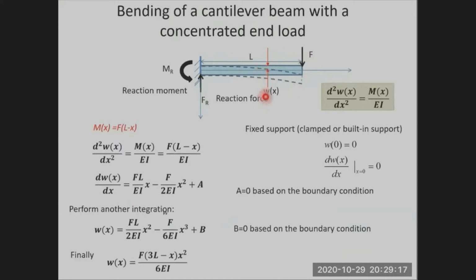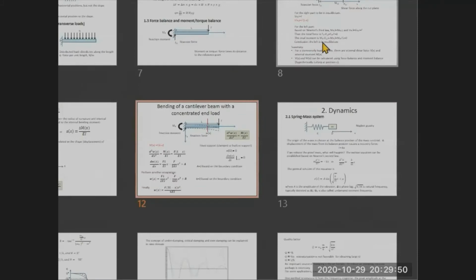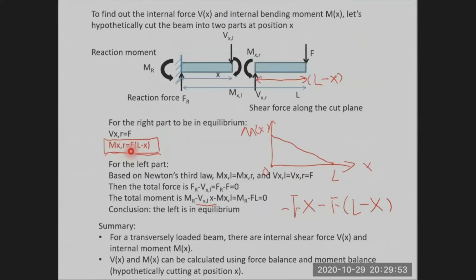We want to calculate W(x) for this case, right? Then we need to use this equation. Then we need to calculate M(x), the internal bending moment. What's the internal bending moment for the cantilever beam under this force? We actually calculated that in this slide.